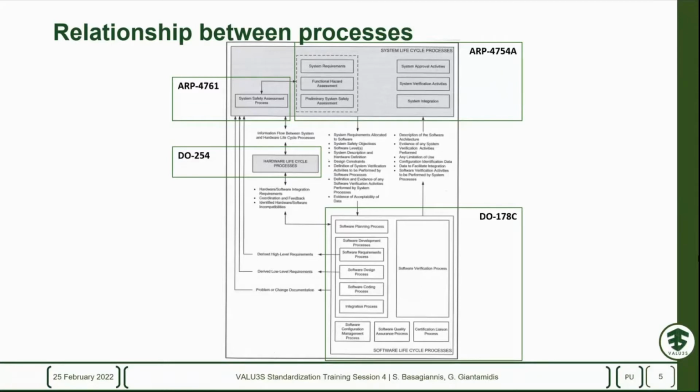So turning to the DO-178C, as I mentioned earlier, there is a series of software lifecycle plans that we have to do when we develop our software, starting from the initial requirements, how to map these requirements to the architecture, how to maintain those requirements down to the model side, so what type of models we are building and which model is for which requirement, and then how this can lead to the software coding process and later on to the overall integration.